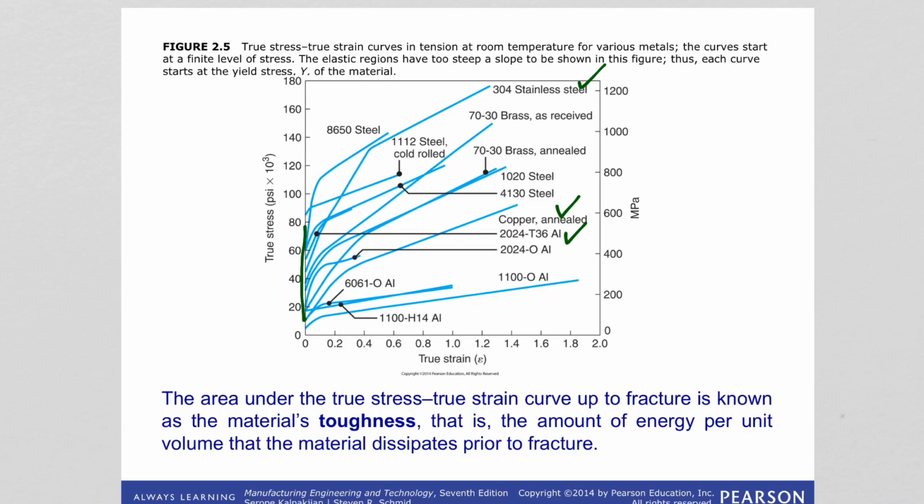That means they are showing different behaviors. Even heat treatment changes properties. For example, for the same brass, if you anneal, meaning heat treat, you can see how the slope is changing, and it is also showing better strength values when you look at the stress strain diagram.